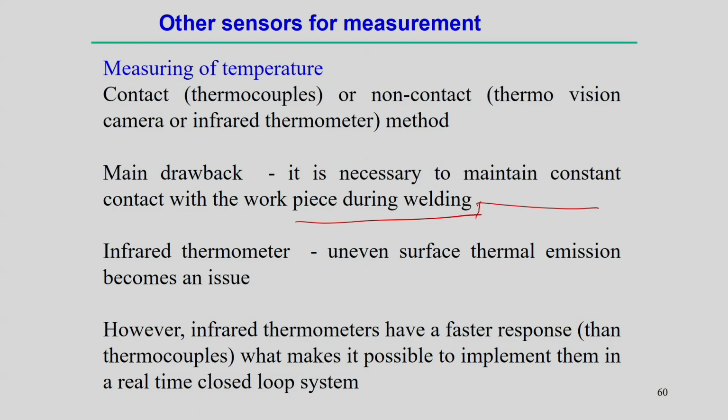Of course, it is not necessary to make direct contact; it is a non-contact mode we can measure. But the difficulty is an uneven surface, because the infrared method basically detects the thermal emissions from the surface. So if the thermal emission is not proper, then it is very difficult to detect in non-contact mode using the infrared thermometer or thermal vision camera.